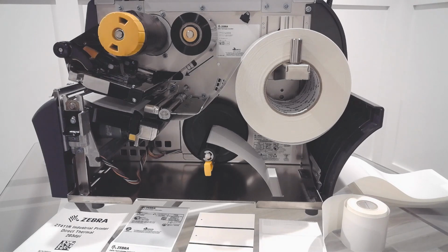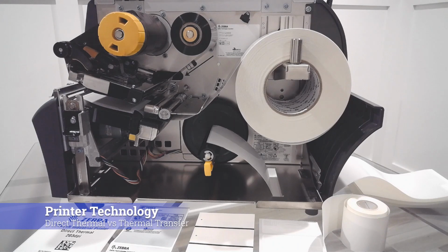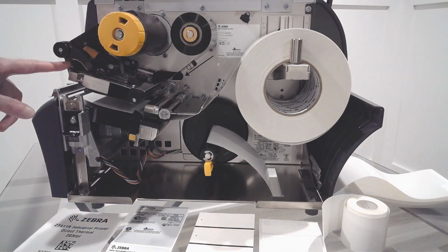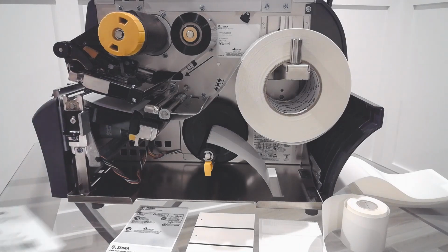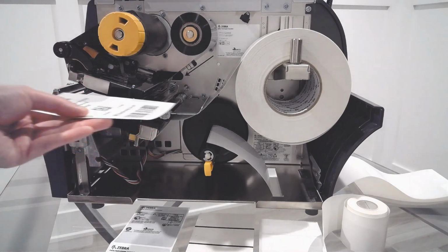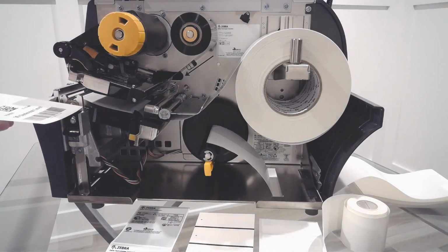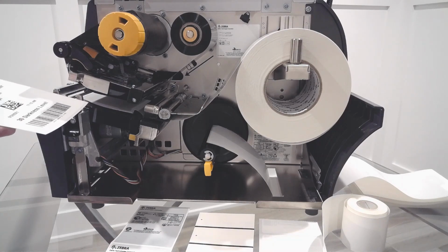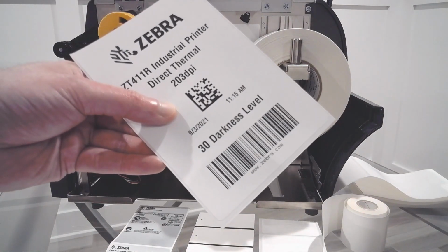This section goes into the basics of thermal printing. If you're already familiar with thermal printing, you can skip to the next section where we will demonstrate the Supply Selector tool. The first set of basic terms to become familiar with is direct thermal versus thermal transfer. Both of these methods use heat from the printer's printhead. The heat from the printhead heats the surface of the media as it passes underneath the printhead. As it passes by, the printhead heat turns on and off depending on the format data sent to the printer. This in turn generates the label.